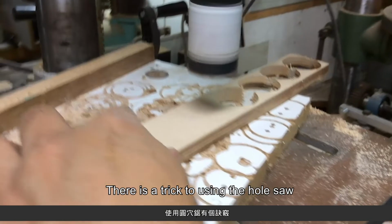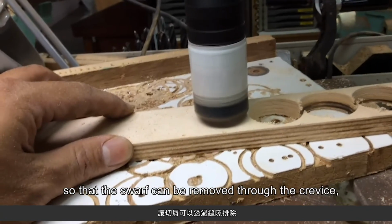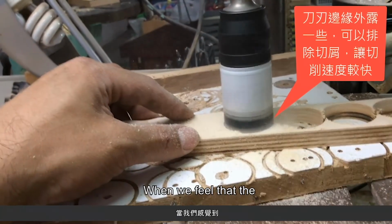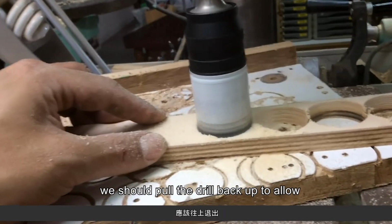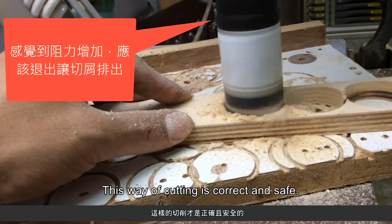There is a trick to using the hole saw. We can expose the edge of the blade to the outer edge of the material so that the swarf can be removed through the crevice. The cutting speed can be faster. When we feel that the drill has more resistance, we should pull the drill back up to allow the swarf to be removed. This way of cutting is correct and safe.